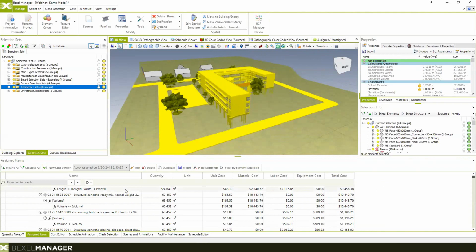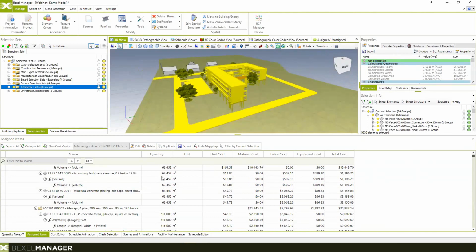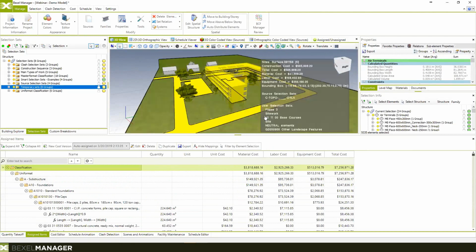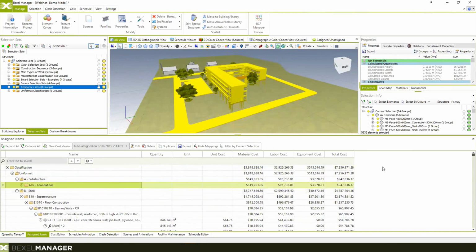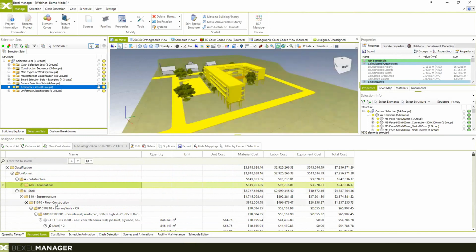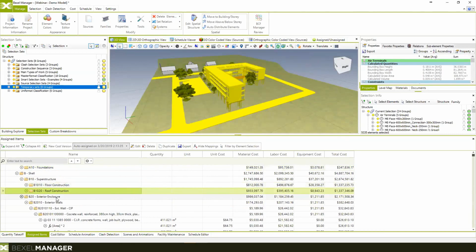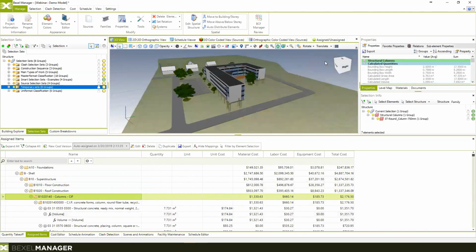In order to show you another useful feature of how you can use this quantification and auto-assign cost items to the 3D elements, you also have a quantity. It means that you have automatically calculated quantification of all your building elements according to the Uniformat classification system, because we applied that one. So for example, if we want to check that, I'm just going to show you how it works. We can select, for example, some specific item. I'm going to find the columns, for example, and I'm going to select all these elements, isolate.